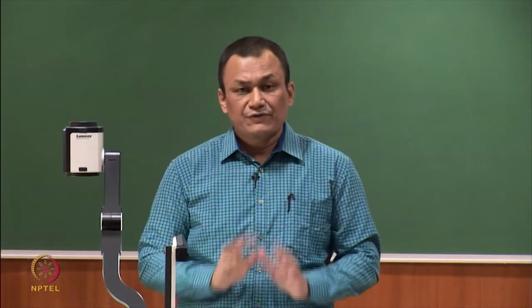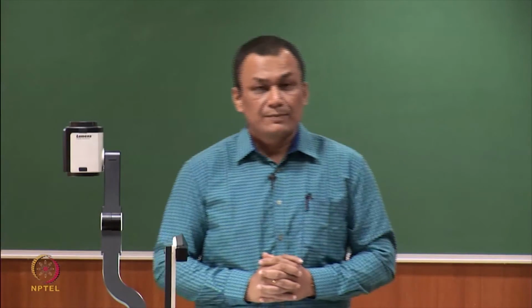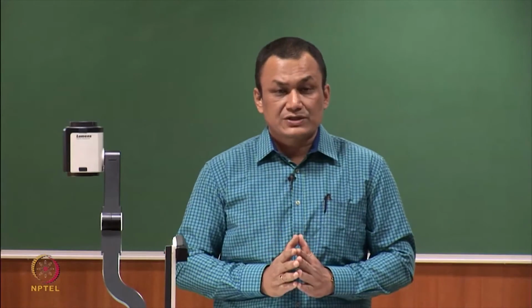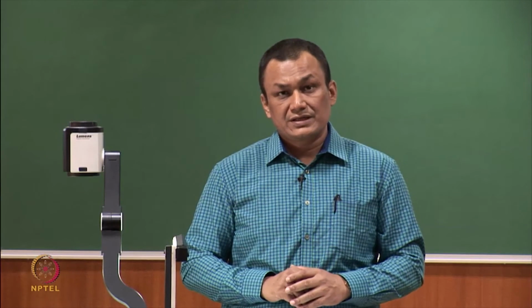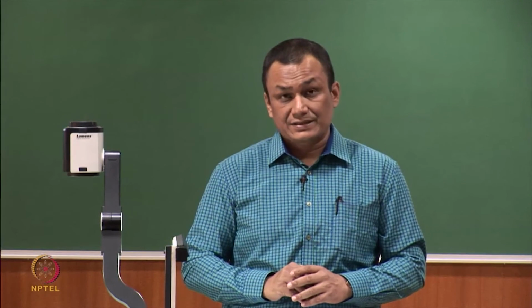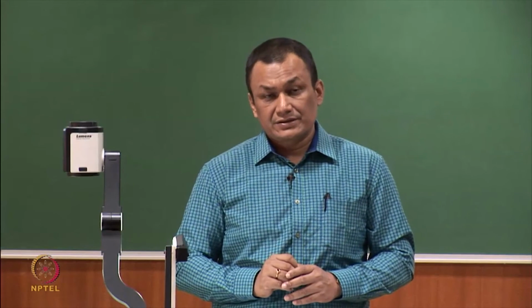So, if we summarize Martindale's model, Martindale's model is based on 4 important assumptions. The basic assumptions are: sliver is prepared from fibers, all fibers have same length, all fibers are straight and they are parallel to sliver axis. The fibers are deposited individually and randomly to form the sliver, and the special assumption is the number of fibers in the cross section of the sliver follows Poisson distribution.